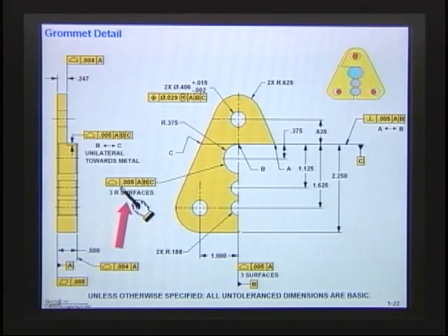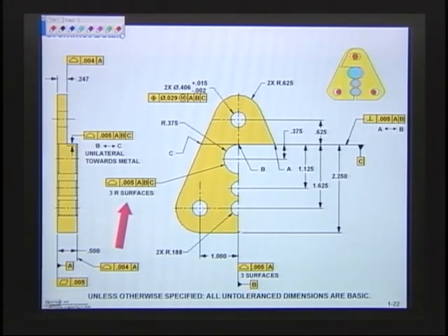As a matter of fact, if you think about it, that's really what I want anyway. When those parts come together here, when the next part comes together and that cable fits in, what I'm interested in is what's the smallest that thing can be and what's the largest that thing can be. You see what that is? It's really nice. It's a profile tolerance. It says that radius will be a 375 radius, and then it can come in by 2.5 and can come out by 2.5. And right there I can tell you what kind of squeeze I have on that cable, anything else.